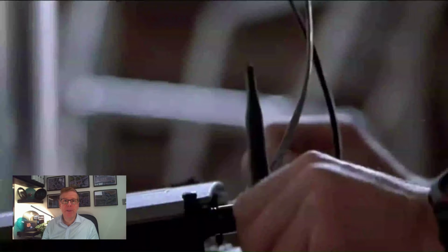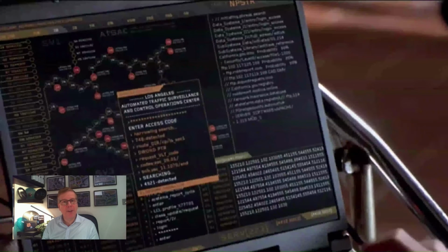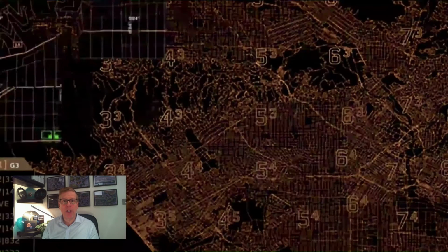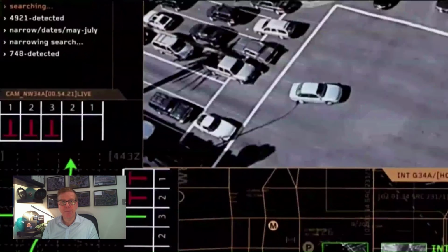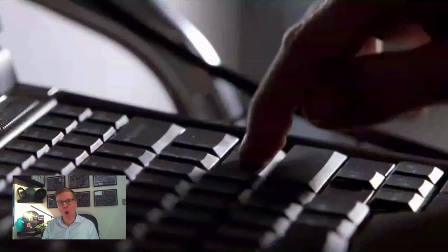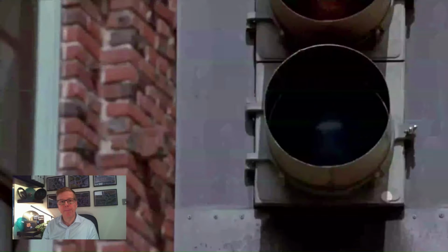This is the most critical safety feature within a TSC, which once programmed cannot be overridden, either locally or via the UTC system. So this Italian Job scenario just wouldn't be possible, to force conflicting phases to operate at the same time.